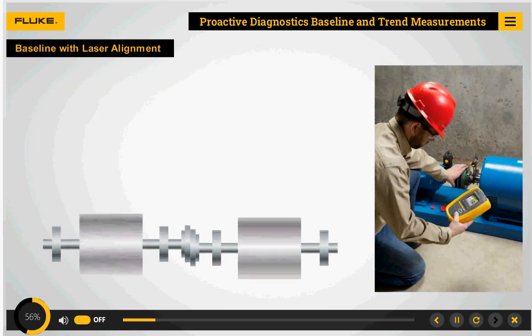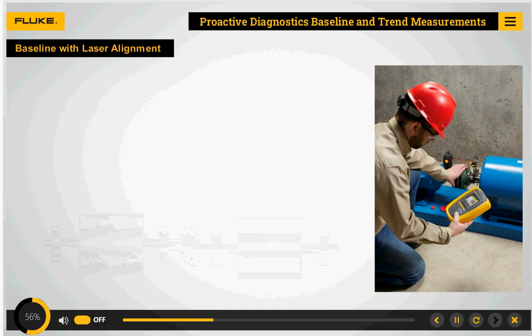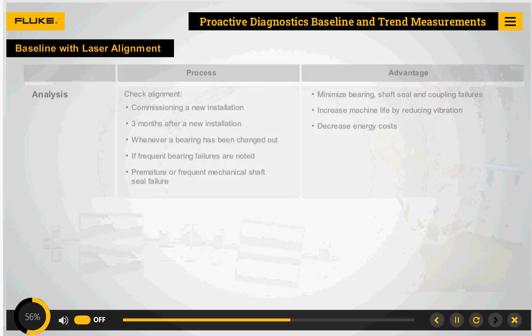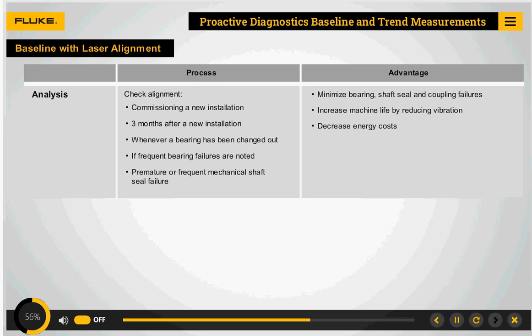Misaligned machines cause higher reaction forces in the coupling, which leads to heat and wear in couplings, seals, and bearings. These worn components cause increases in unplanned downtime, energy consumption, and unnecessary maintenance intervals. Regular precision alignment reduces mechanical seal repairs by up to 65%, and when precision alignment becomes an integral part of pump repair schedules, the rate of pump repairs is reduced by up to 30%.